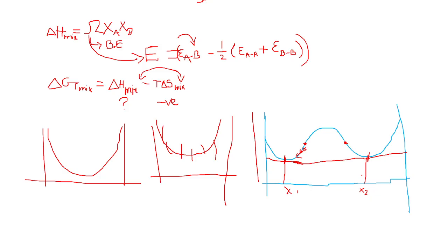So we have even derived that part where the nucleation rate depends upon the undercooling, right? So it follows the exponential path. So once we attain a certain undercooling, the nucleation rate will just burst out. So that's what we see in homogeneous and heterogeneous nucleation. For homogeneous, we need heavy undercoolings. For heterogeneous nucleation, we can go with light undercoolings. You will have a high nucleation rate. Now, undercooling means we are reaching very low temperature.